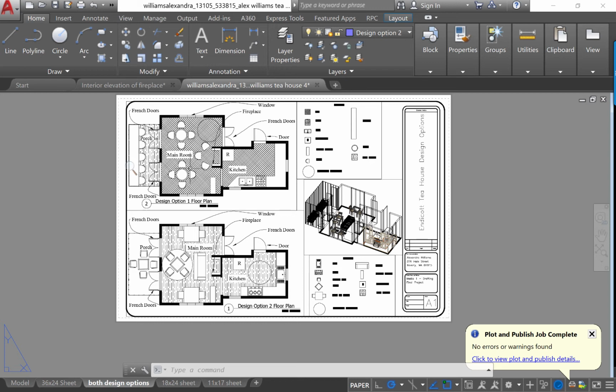And then when you get to the reflected ceiling plan viewport, you just hide those layers that aren't supposed to show up. So to summarize what we learned here, it's possible to put in dimensions and text and other items, and you can control how that text prints by using the annotative text style and the annotative dimension styles.